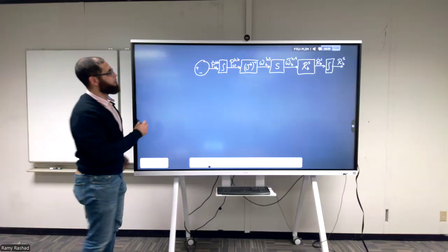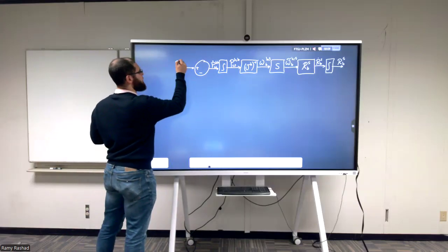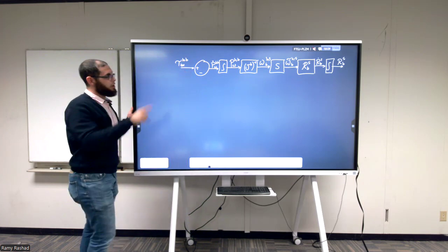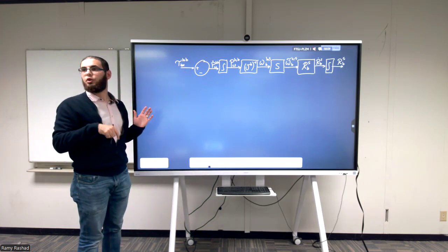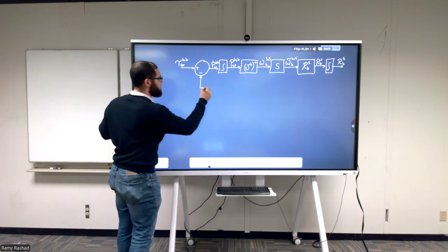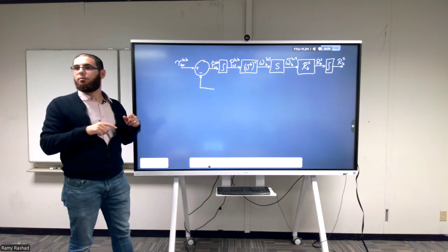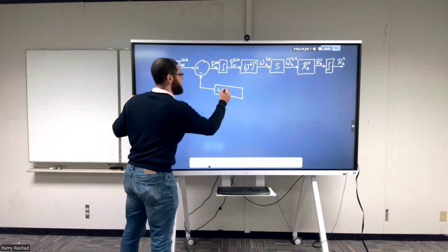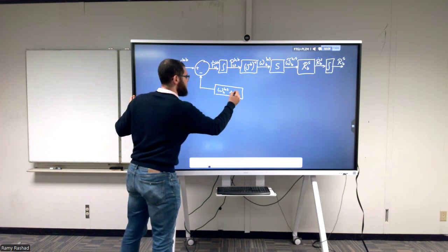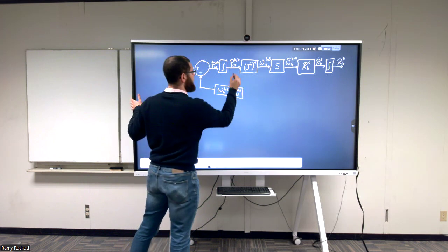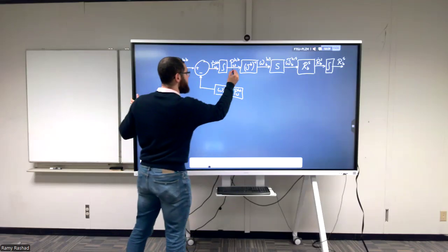For the plus term, I add all of the torques applied on the body B. And there's a correction term that involves a cross product between omega and P, both in the B frame. So I need to feed back this guy and this guy.